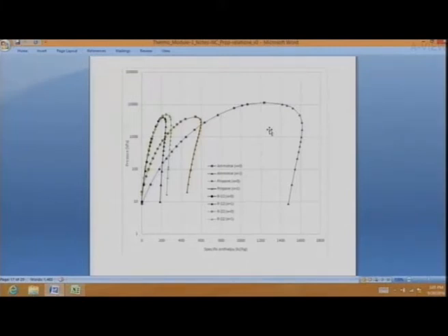to be very, very careful, because in all these cases, specific enthalpy, which is here set to 0, is decided quite generally as per the wishes of the person making the property tables. In these materials, the specific enthalpy hf at 200 Kelvin has been set to 0.